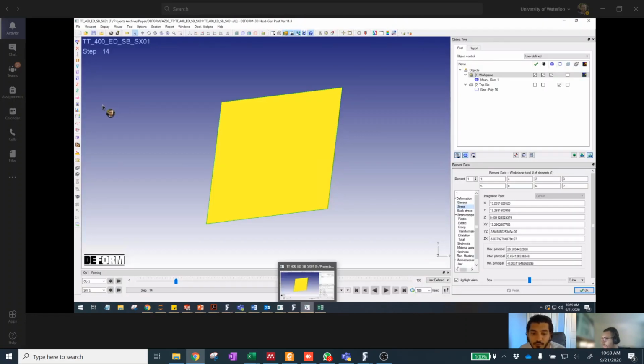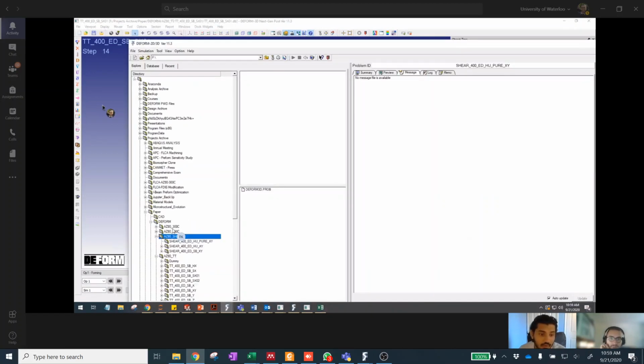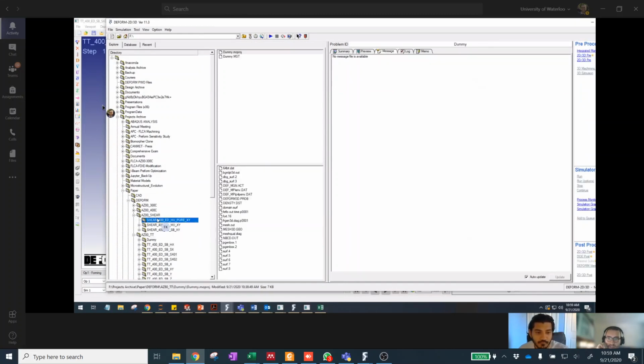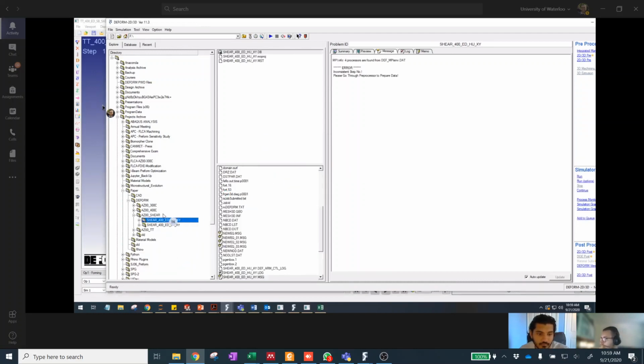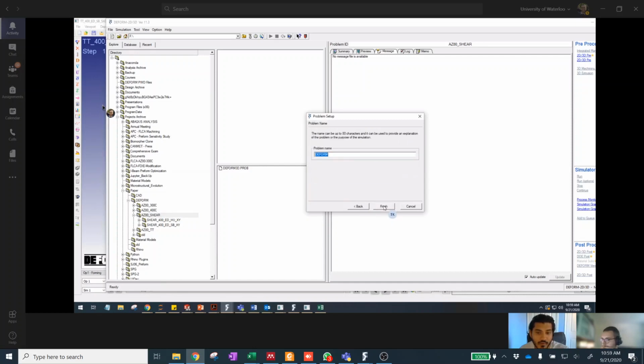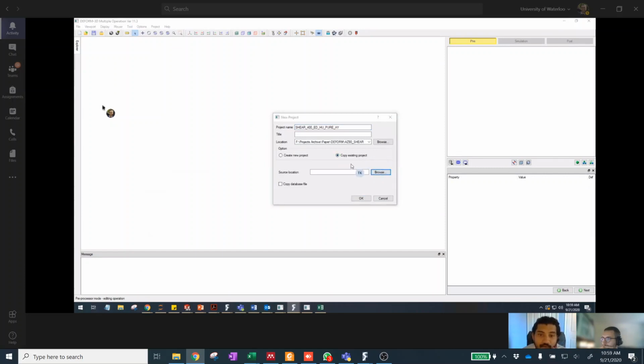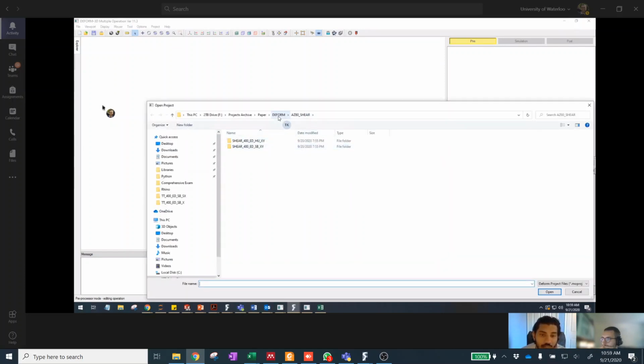So I'm going to go back to setting up Hugo's material model with this model and see if we get a closer XY value. Because ideally what you should be getting is no axial stresses. If it's done correctly and the boundary conditions are correct, you should just be getting shear stresses, kind of intuitive with the name pure shear. So if you're getting any axial stresses, most likely you're over constraining the nodes. Oh, what was this one?